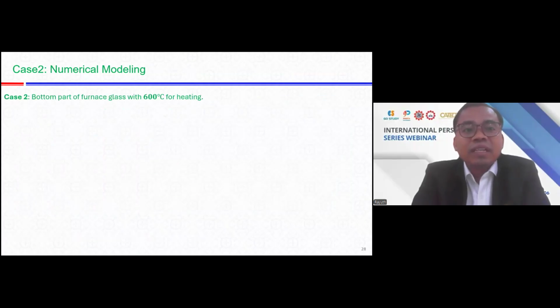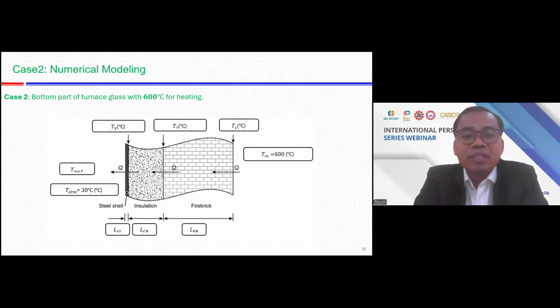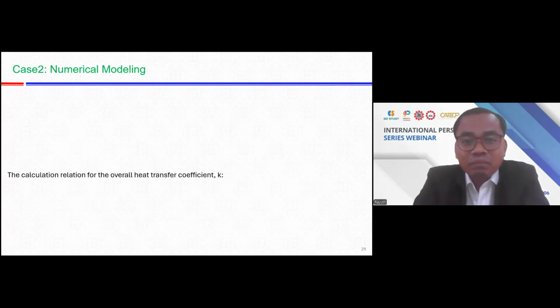And for case study two, I mean case two, not case one, I chose a higher temperature. Inside is 300 degrees Celsius, and the surface I chose 50 or so. And for the materials, the same: inside ceramic bricks, insulation, and the surface stainless steel.